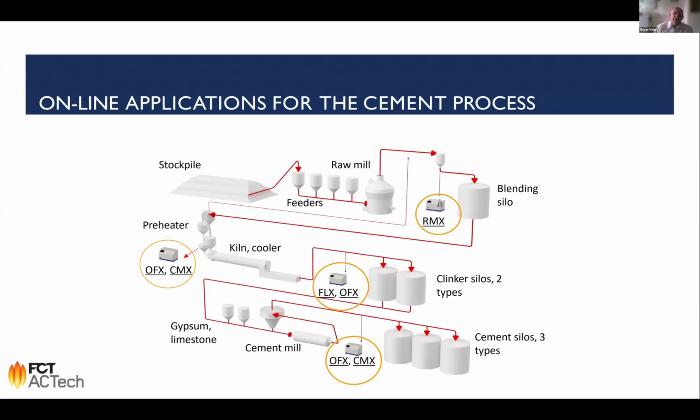In particular, if you use a lot of alternative fuels or similar materials, then it can cause a clogging in the preheater. And in the worst case, it can block the whole process, which will require a shutdown of the plant and cleaning of the specific parts, and you will lose a lot of production and money. And also the startup usually is not that smooth, so you want to avoid it.